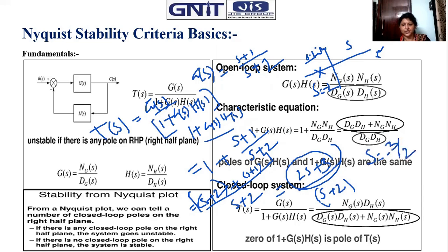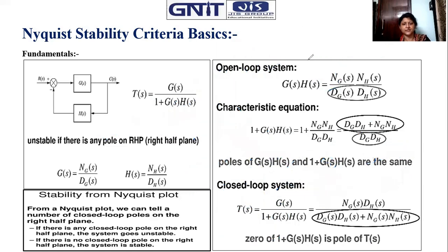Now it is clear. Again, I am defining this with a certain example. Suppose we have G(s) equal to (s plus 1) divided by (s plus 2). What is the open loop pole position? In the open loop transfer function, there is a pole at s equals minus 2, in the S-domain representation with the sigma and j omega axes.